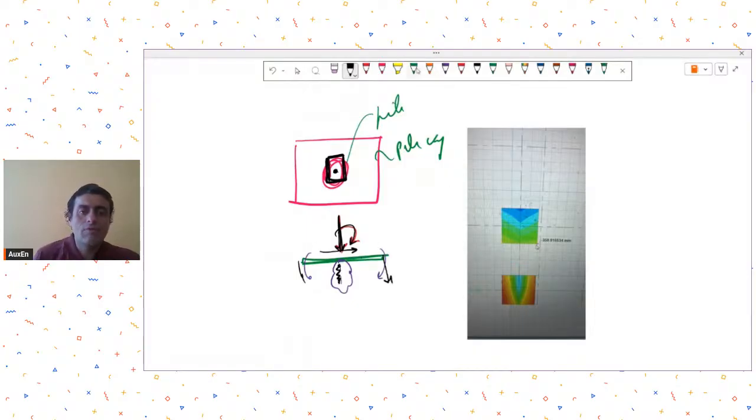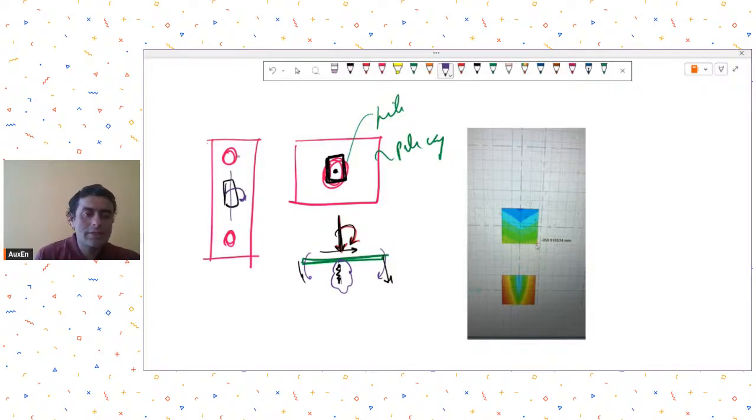Okay, same thing you may find in a two pile cap also. If you have this kind of a pile cap, and let's say you had a pile and this was your column, and suppose the actual movements were about this axis. Now about this axis again, what will happen is that you have modeled the pile with single point springs. So again this pile cap has no restraint, so to say, for movements about this direction in the column. So again you will see very high deflections, as you are getting over here.